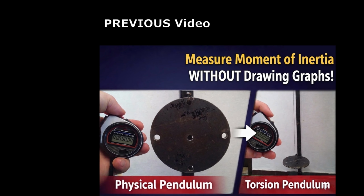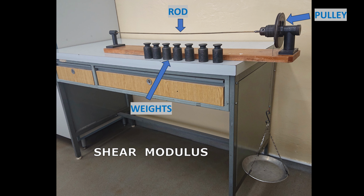In the video titled, How to Measure the Moment of Inertia of a Physical Pendulum, plus Rare Torsion Pendulum Method Explained, we measured it for a wire using time measurements of a torsion pendulum. Now we will measure it more directly for a brass rod, using the torque applied to the rod and the resulting angle of twist of the rod. All we need to do experimentally is twist the brass rod in a direction perpendicular to its axis of symmetry with weights and measure the corresponding angle of twist of the rod.